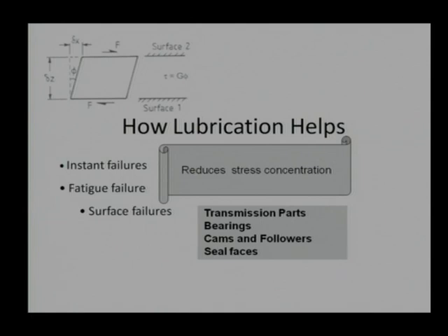If we want to represent it in terms of stress, we can say that tau is equal to G into phi. Here G is the shear modulus. Shear modulus is generally given in terms of gigapascal. For most metals it is in gigapascal. For polymers, it may turn out to be megapascal. But if the shear modulus is reduced, the shear stress is going to reduce for the same shear deformation. So, that is the advantage.